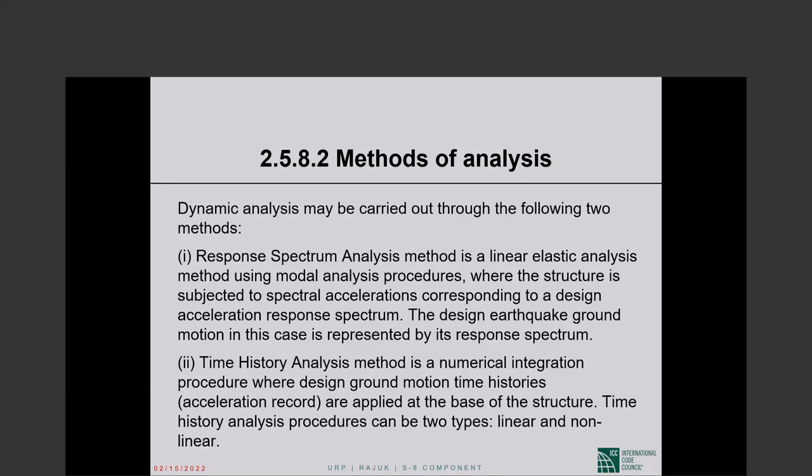However, if you recognize reality and assume that in the process of responding to the ground motion that we have imparted to the base of our structure, selected portions of selected structural members become inelastic and undergo inelastic deformations, then what we are doing is inelastic response history analysis, which is the most sophisticated analysis we can do.